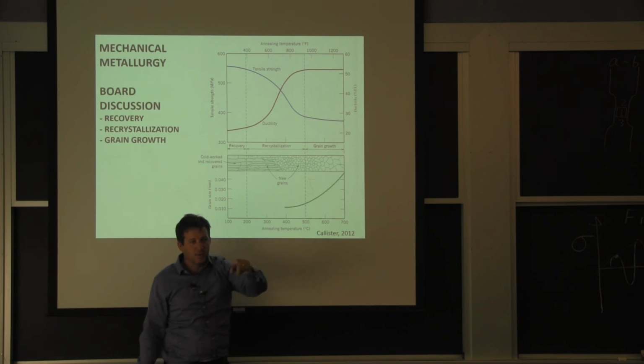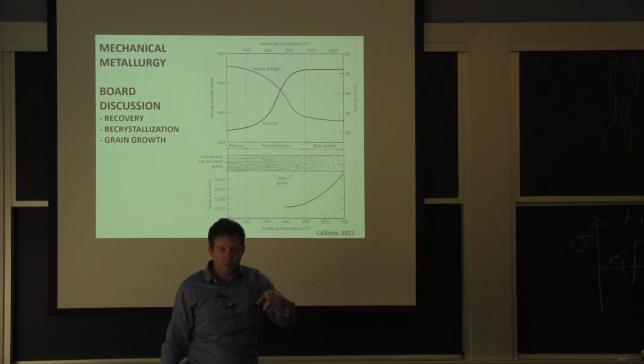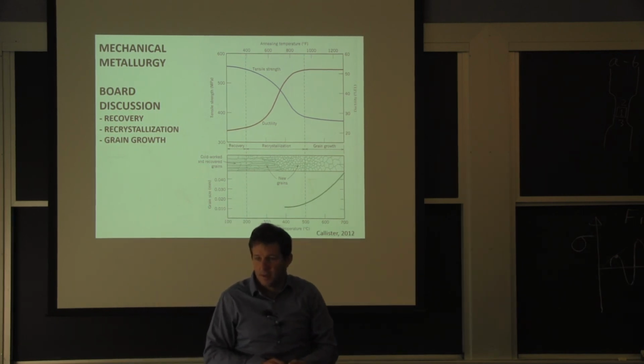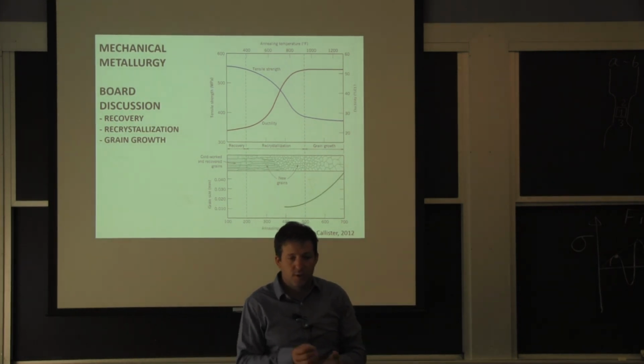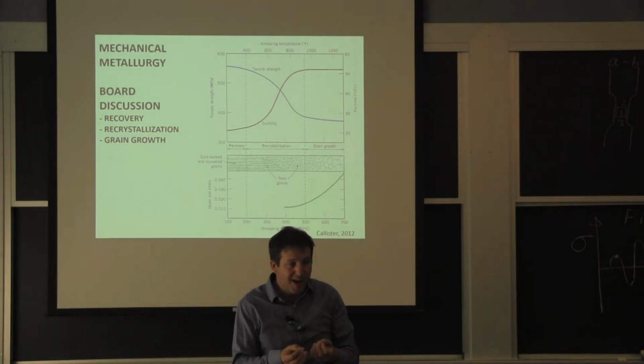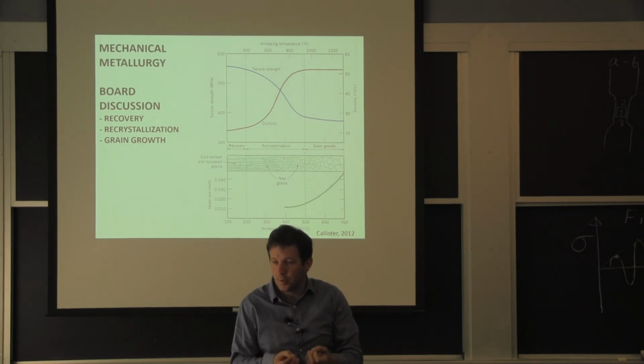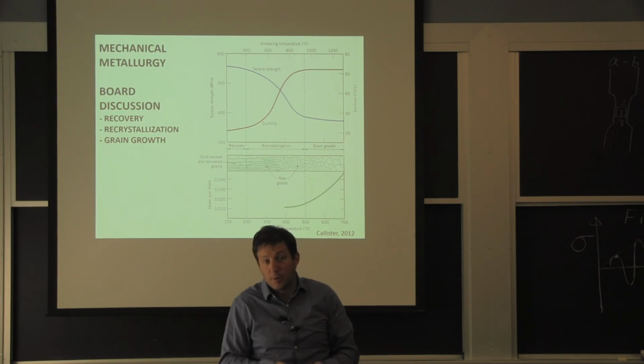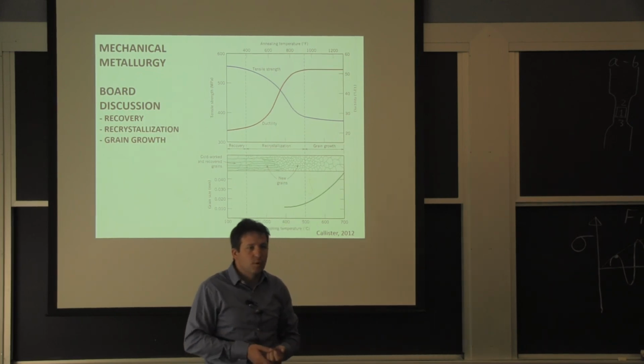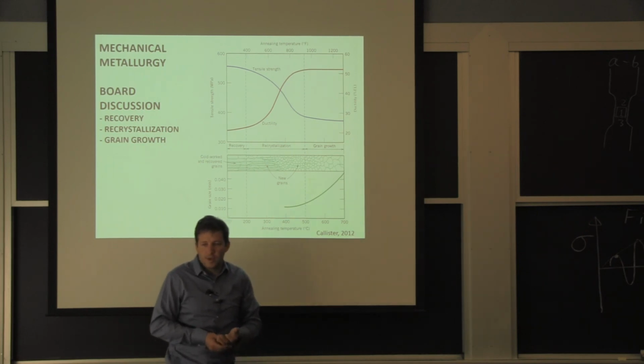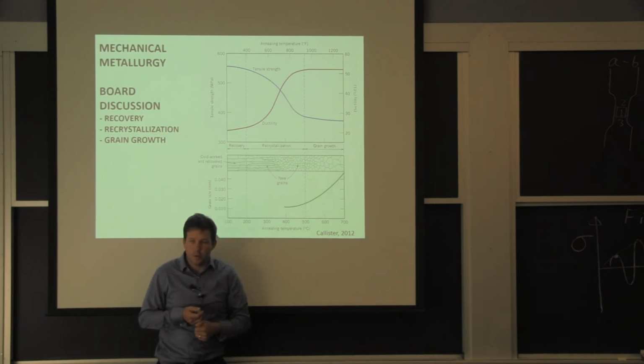So that 600-degree copper sample you see with the big peeling effect is essentially a situation where there were fewer grains that manage to form because we were at low temperature. It takes time for them to form, yet when they formed, they grew, and we call it abnormal grain growth. And it's a problem mostly with pure metals. It's a big problem for pure aluminum.